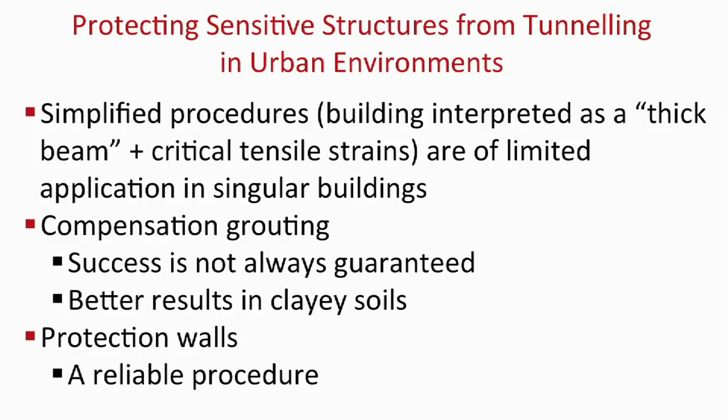My overall impression is that I don't like it too much. Sometimes you have to use it. It's difficult to control. I think there is a tendency to escape a little bit from compensation grouting. This is my feeling. But in general, in clay soils, you get better results. In sand, it's quite difficult. Now, protection walls, in my opinion, are a reliable procedure, but sometimes you cannot use them, because if you go under the buildings, you cannot use any protection wall.